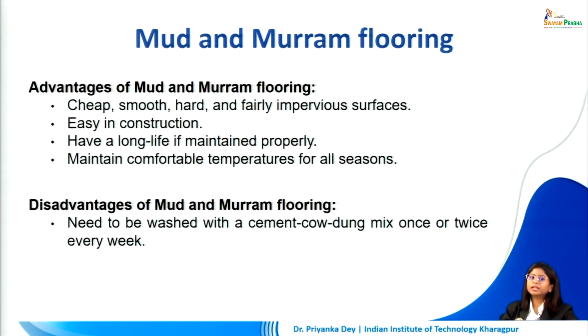Now, there are several advantages to using mud and muram flooring. This is very cheap, smooth, hard, and it provides a fairly impervious surface. So, it is a good choice for low cost constructions. It is easy to construct, locally available unskilled or semi-skilled laborers can apply this. They have a long life if maintained properly, of course, and they are able to provide comfortable temperature through all seasons. So, for climatologically comfortable houses, it is a good choice.